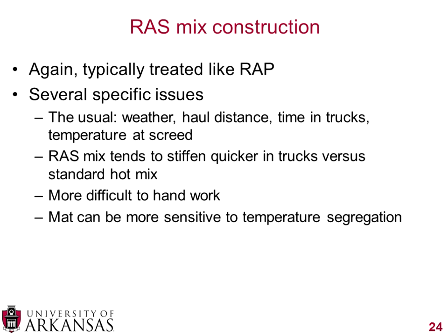Some similar trends with the construction side of things. Again, you typically treat RAS mixtures like you do RAP mixtures. There are some specific issues that they called out, and there's the usual. You want to be cognizant of the weather, the haul distance, the time that the RAS mix is in the trucks, and then also the temperature at the screed. All of these things are considerations.